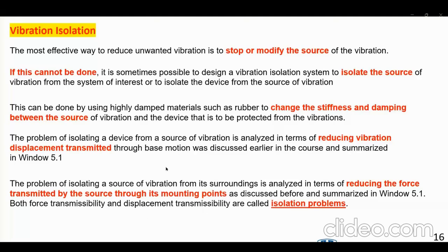In other words, when you put these isolations in place, you basically either reduce the force through the foundation, or in the case of, for example, base excitation, such as a car going over a rough road, you're trying to reduce the displacement transmissibility.